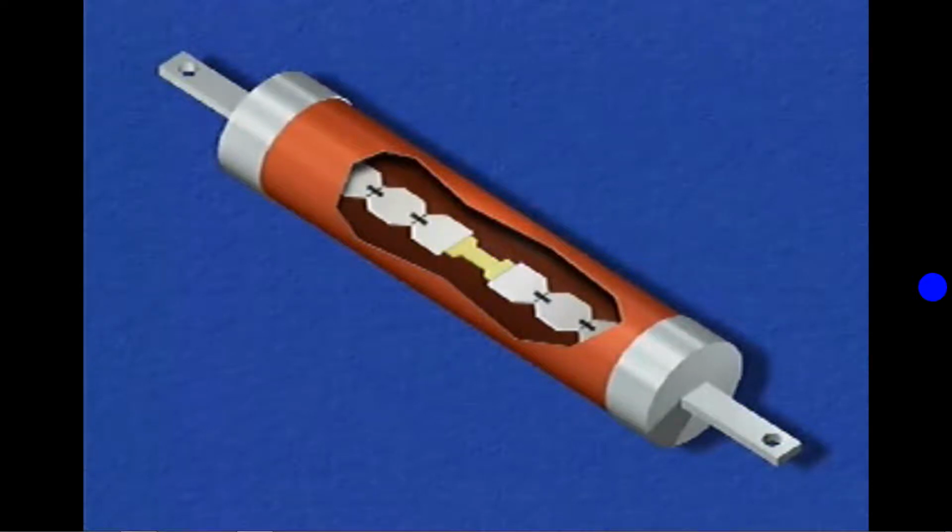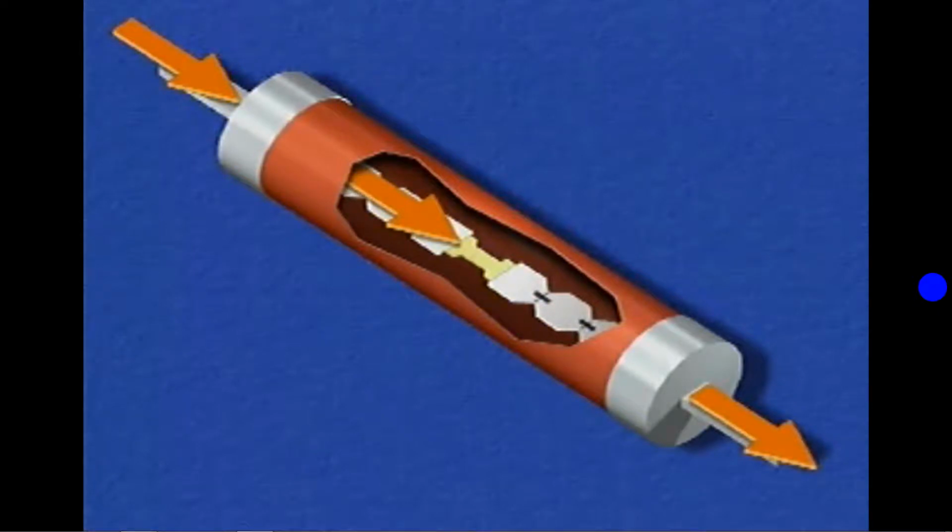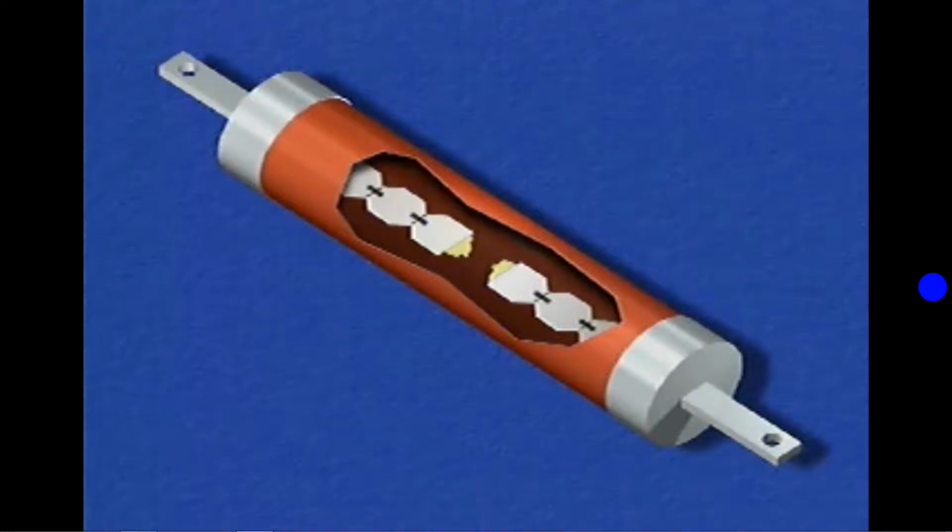The short circuit elements work like one-time fuses. They melt when their current limit is exceeded. The time delay element is made of a special alloy that is designed to allow some momentary overload to occur. However, if a small overload continues for an extended period of time, or if the magnitude of the overload increases to a sufficiently high level, the alloy melts all at once, opening the circuit.